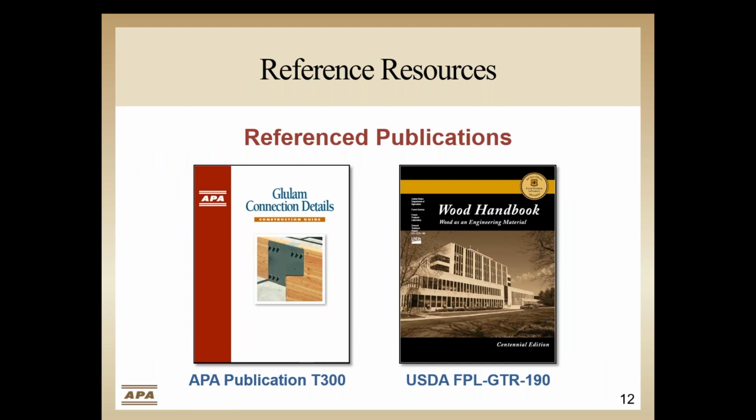Now that we have a basic understanding of wood as a material, we'll start looking at some connection design and detailing. I'd like to start by noting that a lot of the details and examples you will see today can be found in APA's Glulam Connection Detail publication. Proper connection details are important to the structural performance and serviceability of timber frame structures. This illustrated guide shows correct connections as well as common connection errors involving glue laminated timbers. The concepts shown can also be applied to most wood applications.